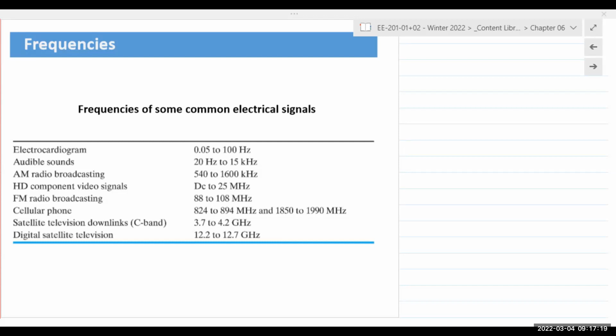If you're tuning your radio station, there is a tuner at the front end. You're setting the frequency that is going to be accepted in the FM radio as 99.7. There's also a filter. The filter at the front end of every device is only going to allow that particular frequency to come in. If you want 99.7, it's only going to allow 99.7 to come in. Everything else is blocked out.